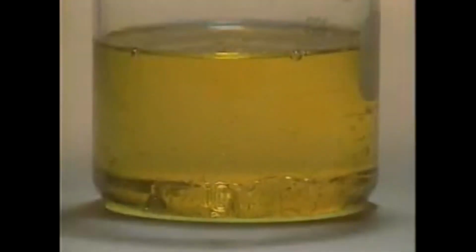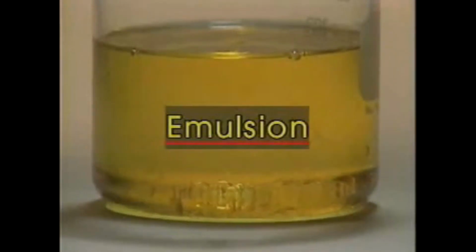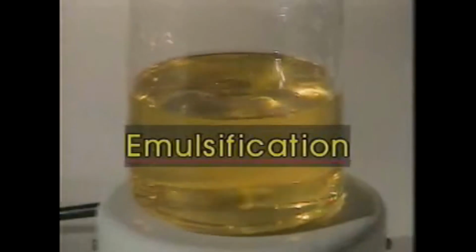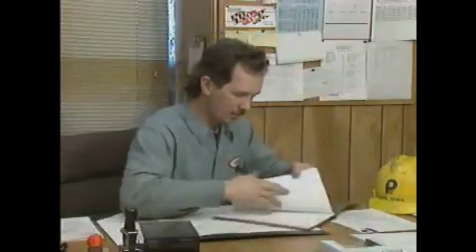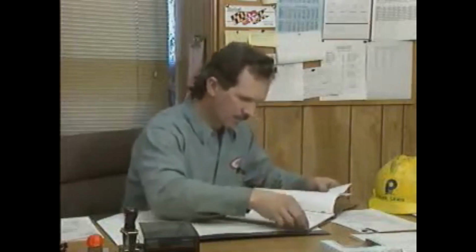A lubricant's resistance to forming an emulsion is also important. Basically, an emulsion is a mixture or suspension of components that are difficult to separate once they've been combined. The process that causes the formation of an emulsion is called emulsification. A lubricant that resists forming an emulsion is usually desirable because an emulsion of lubricant and water has poor lubricating qualities. Equipment manufacturers generally specify appropriate lubricants for their equipment, depending on how the equipment will be used.